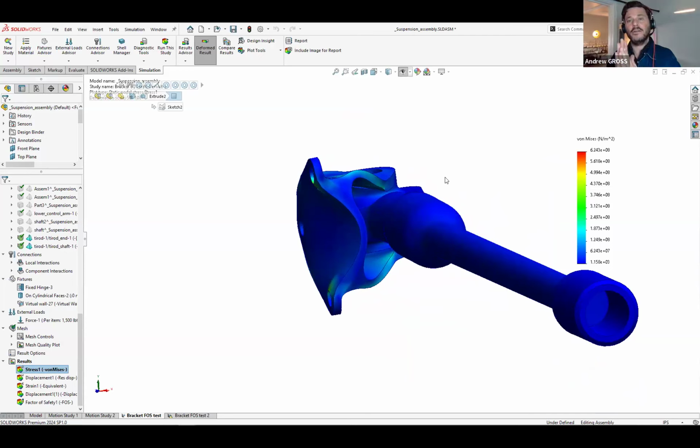So the roller slider, think of it like the suction cups you may have had as a kid, where you stick them on the glass and can move the suction cup around. You can't pull the suction cup off, but it can slide along that face. That's kind of what the roller slider does. It is stuck to that face. It cannot move in or out of that face at all, but it can move along the plane. That's super useful information. Thank you.